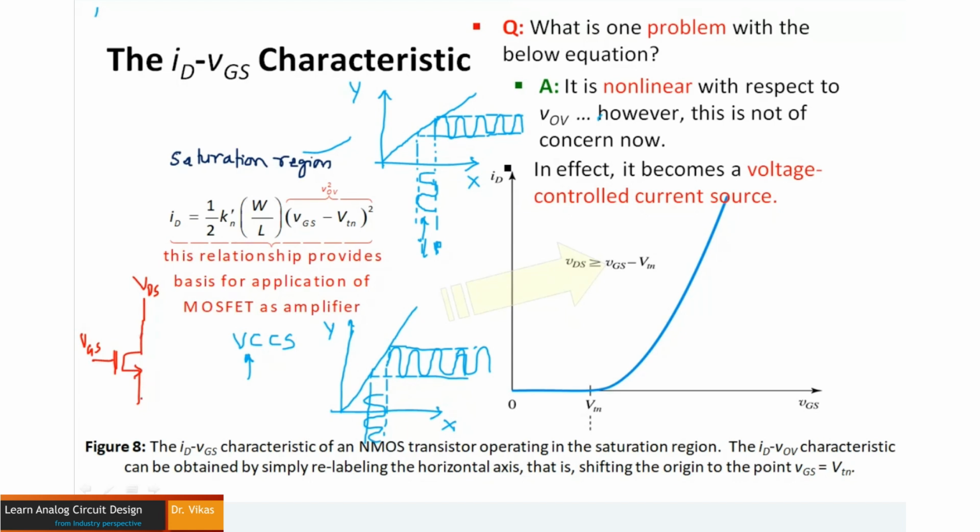and as a result this MOSFET has entered into the saturation region, because I want to see how my MOSFET is going to behave as an amplifier. I'm taking a simple single MOSFET. So I have given a VDS and a VGS, satisfying the condition VDS greater than or equal to VGS minus VT. That means this MOSFET is now pushed into the saturation region.